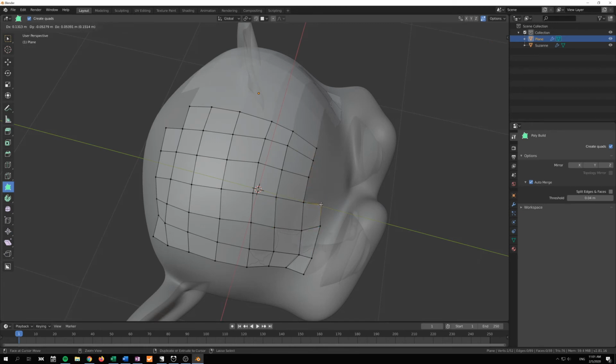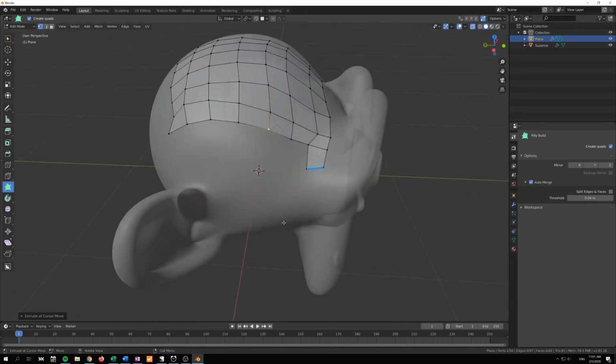remove. So I would suggest that to either have snapping off and hold Control for most of the time, and then if you need to adjust a few vertices, you release it and press it, release it and press it. The other way is to have snapping turned on and work with the edges like this.